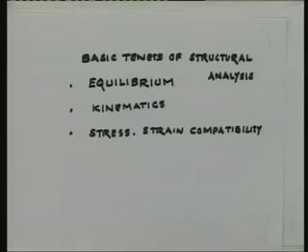And the third and final tenet is very, very basic, and that is stress-strain compatibility. In other words, when you have loads acting on a structure, the body deforms. Due to the deformation of the body, strains are set up at various points in the structure, and because of the strains, stresses are developed, and these stresses are essentially the internal forces developed in the body.